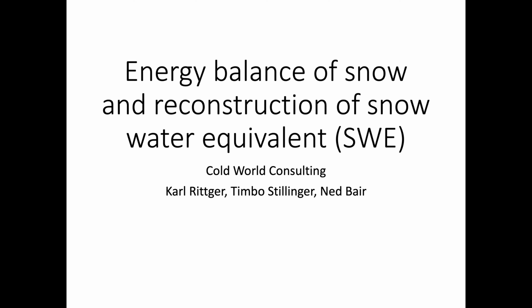These two concepts are directly tied together as we use the energy balance, which can tell us about the volume of snow melted each hour or each day that we use to look at the past, and build up a snowpack as a sum of melted snow. However, first we'll do a quick review on concepts from the previous lecture.